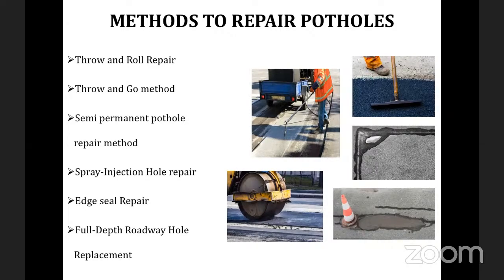First we will see what the throw and roll method is. This figure will tell you about the throw and roll method. In this method, first the material will be placed in the pothole. And before placing the material, they should see that there is no water or debris.